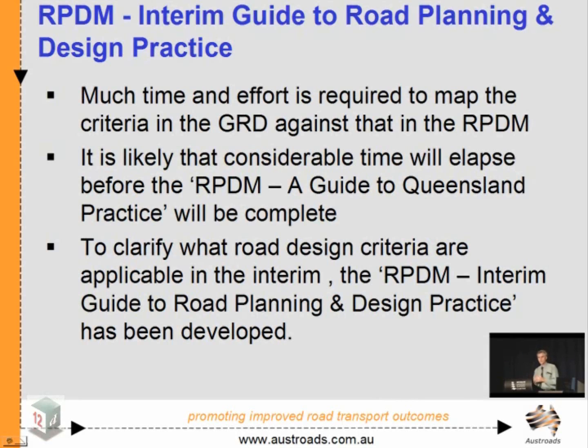But we did say though that if Austroads gives you a better answer and it's more fit for purpose in a particular situation, feel free to use it, but just document the use of a value in Austroads. If it's different to our Road Planning Design Manual and it's less conservative, document it as a design exception. So what we don't want you to do is feel that you can't start using the Austroads document, but just document it as a design exception in the interim until we come up with our companion document.